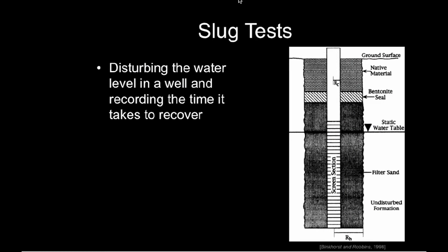So we measure hydraulic conductivity by conducting slug tests. To start out, we used these wells, which are not like wishing wells, so don't think that they're these massive things in the ground. They're just pieces of PVC pipe about 1 to 2 meters long. There's a well screen, which is the bottom section of the PVC pipe, which has small holes or slits in it that allow water to pass through the PVC into the well, and so the water level inside of the well will be the same as the water table outside of the well. There's also a small device called a pressure transducer at the bottom of the well, and that just records water level changes.